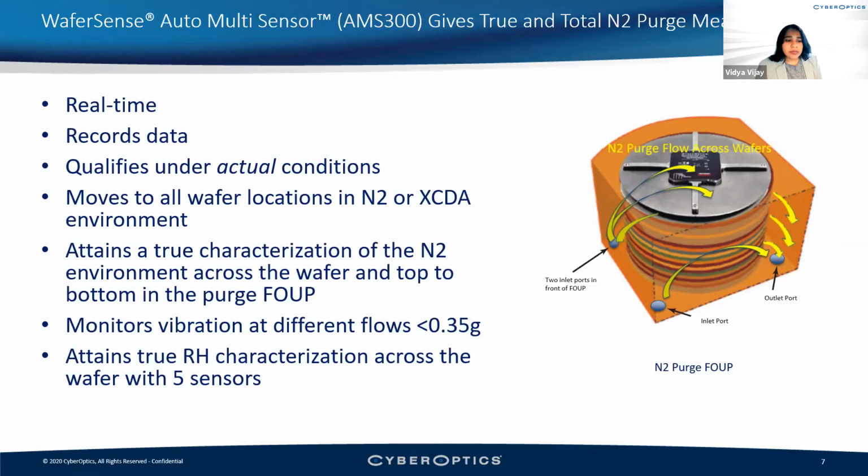And while we were thinking about the humidity, we had these sensing modalities separated in the wafer form, but it helps some applications if we also know the vibration. So there is a vibration sensor and a leveling sensor in this. If we know the vibration as it is traveling across many chambers and stations in the tool, that may help as well.